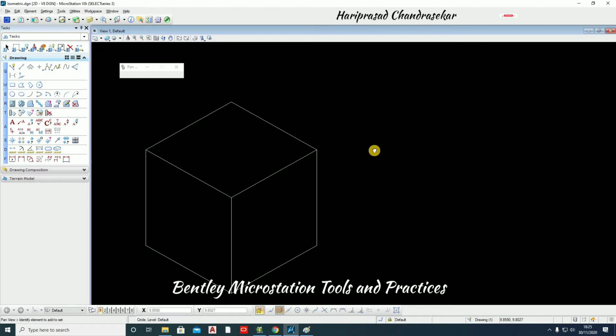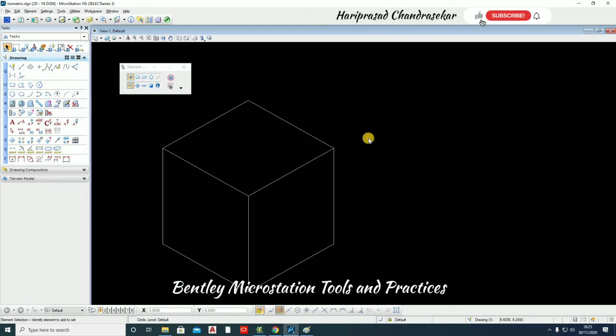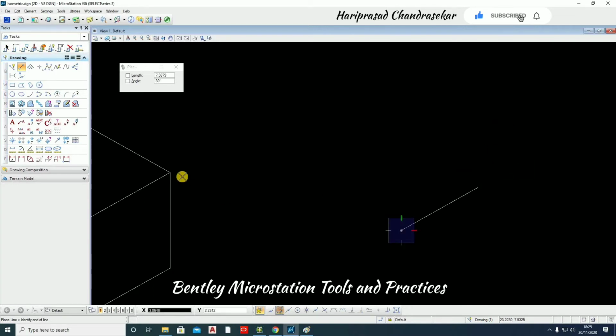Now what we can do is first activate the isometric snaps or isometric tools. For that you need to click this lock icon and then select isometric. Once you have selected isometric, when you're drawing a line, it will automatically go isometric. Now you can easily draw. No need to put an angle at all. 5 and then right click, and this way 5 right click. Now you need to click there. 5 and then right click. Left click and then right click.